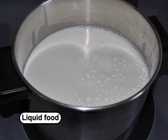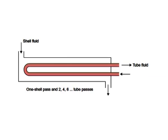Another common type of heat exchanger used in the food industry is a shell and tube heat exchanger, and it is used for applications such as heating liquid foods in evaporation systems. As shown in this figure, one of the fluid streams flows inside the tube while the other fluid stream is pumped over the tubes through the shell. By maintaining the fluid stream on the shell side to flow over the tubes rather than parallel to the tubes, we can achieve higher rates of heat transfer.